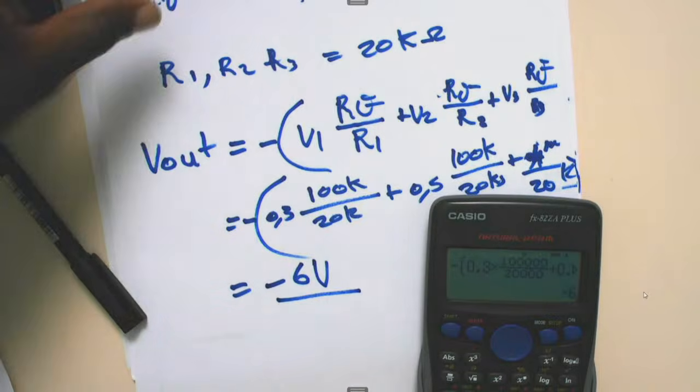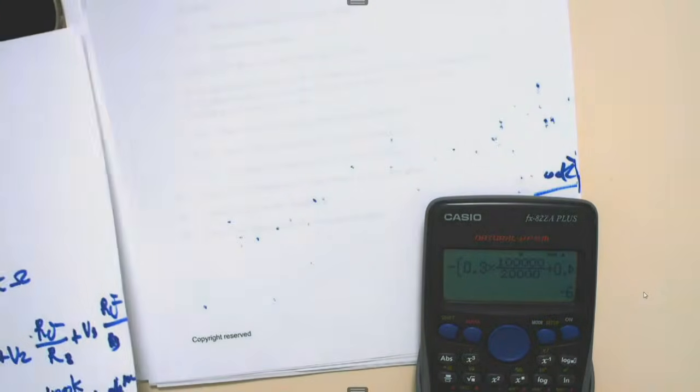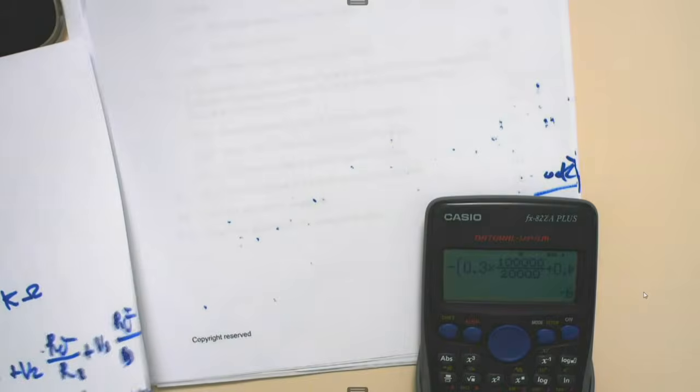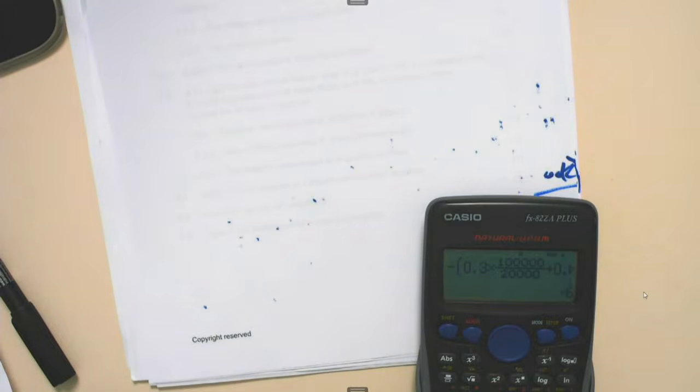So we proceed. We're saying give a reason why the amplifier is not saturated. The reason is that the gain of the amplifier is determined by the ratio of the feedback resistor to the input resistance of each branch. Oh, sorry, I'm on to 4.7.1 now.